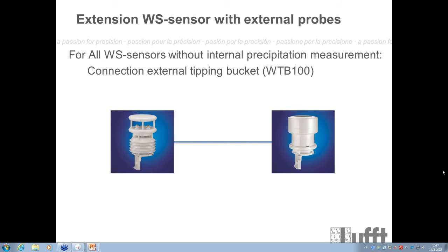So what do you mean with troubleshoot? Normally if you get a problem, no communication, that's a hardware thing, you know. You cannot do a troubleshoot with the software in this case. How will you do that? There is no communication. How should the software then tell you what the problem is if there is no communication? So you have to check this problem yourself. Normally it's a power supply problem, a communication wiring problem, or the sensor is defective. We cannot implement that. That's not possible in this case, because how should the UMB Config Tool know what the problem is if it has no communication?